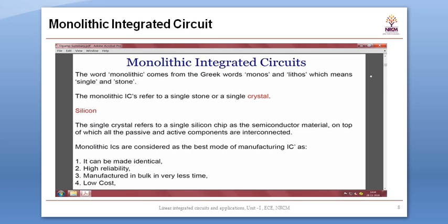So, another type of integrated circuit is the hybrid IC. In a hybrid IC, passive components such as resistors and capacitors and the interconnection between them are formed on an insulating substrate. The substrate is used as a chassis for the integrated circuits. The active components such as diodes and transistors as well as monolithic integrated circuits are then connected to form a complete circuit. For this reason, low volume production methods are best suited for hybrid IC technology.